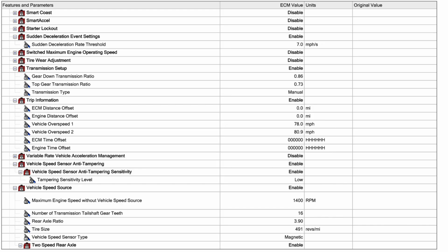Starter lockout, that'll be enabled so that the engine won't crank at certain times. You might see that on a commercial bus where they have a side door, and if that door is open, or if there's a back door in a school bus that's open, the starter will be locked out. It won't start till the driver closes those doors.